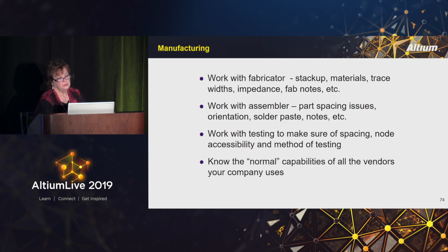Work with your fabricator. Be sure that you have a good relationship with fabricators, assemblers, test people. Know what the normal capabilities are for each of these vendors, because you don't want to be sending them something that is beyond their capability to do, or it's going to stretch their limits. You want to know what is normal for them to do and where they're going to flip over to an upcharge. And if vendor A flips to an upcharge before vendor B, you might want to go to vendor B. You don't want to spend more for the same thing.